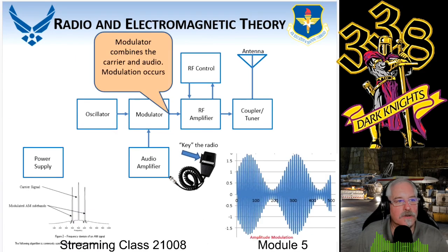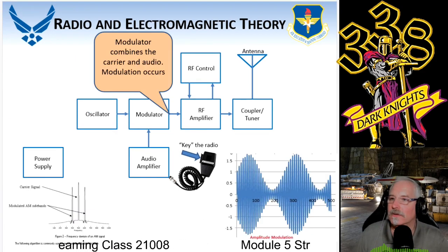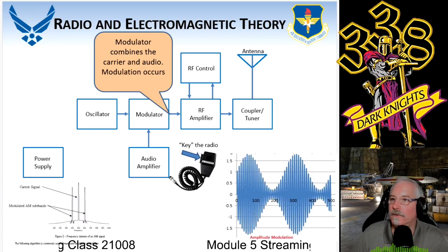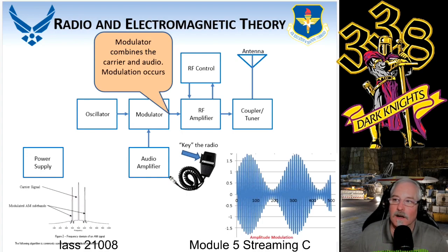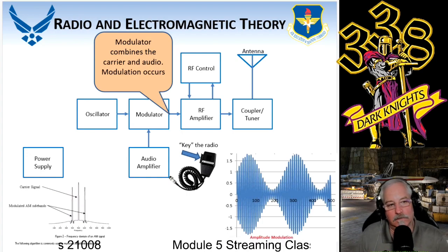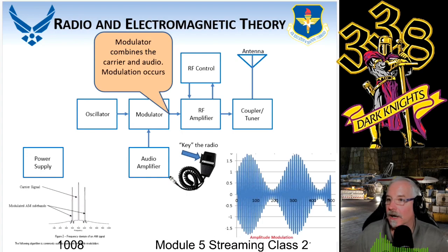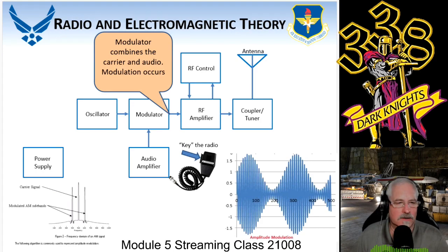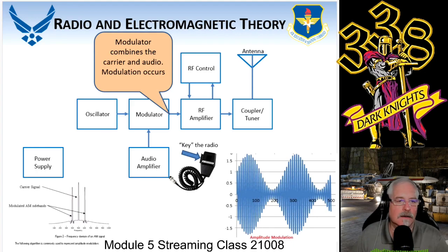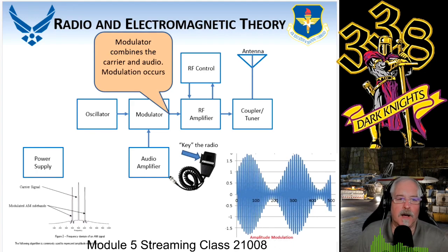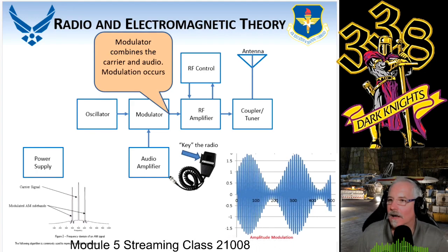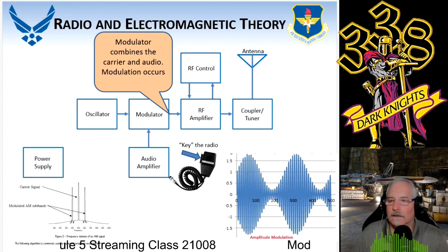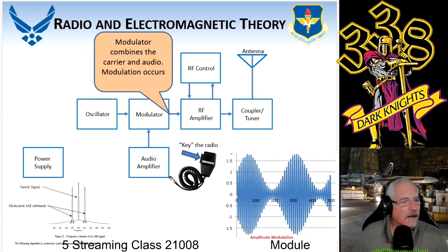When we get to the modulator, it's going to combine those signals. And you can see with the spectrum analyzer on the bottom left, you're going to have 3 signals. And when you look at the O-scope, you can differentiate between the upper and lower sidebands on that carrier right there, and it looks like it's about 90 or so percent modulated, so it's a good modulation there. And the big thing about this, where in the heck did the audio go?